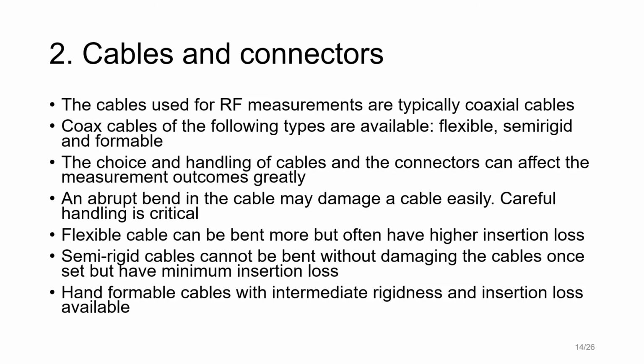So all cables must be handled carefully, since repeatedly bending the cable beyond a certain acceptable range or acceptable number of times can damage the inner core and sometimes the shielding. So using abruptly bent cables will show up in the measurement outcomes and it will affect signals of different frequencies in different ways.